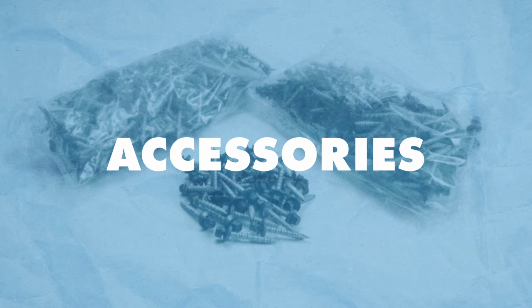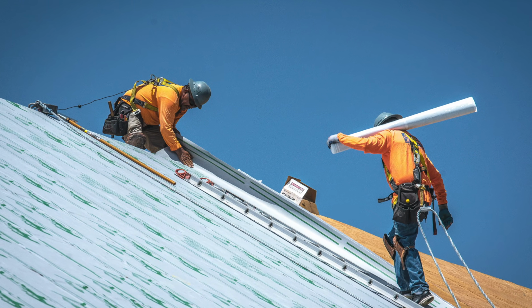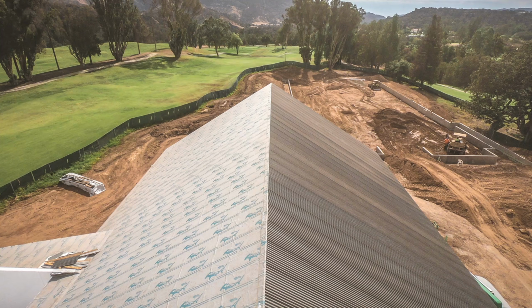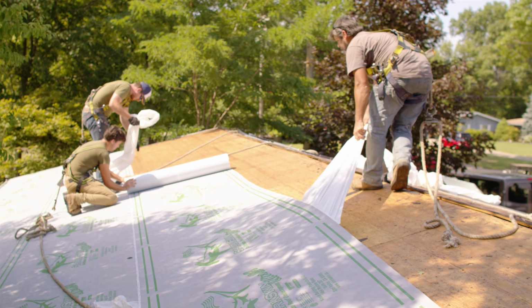Let's look at a brief overview of some standard accessories that go into exposed fastener metal roofing and standing seam metal roofing. Installation of an exposed fastener metal roof first requires an underlayment, a barrier material that is applied to maintain a water-resistant or waterproof environment under the roofing metal. I already mentioned foam closures earlier in the video. They are molded to perfectly match the panel type being installed so they can effectively stop up any gaps that occur in areas like the eave and ridge.